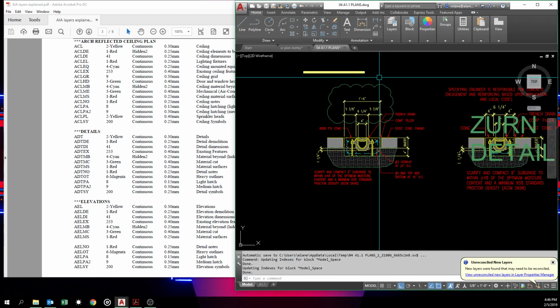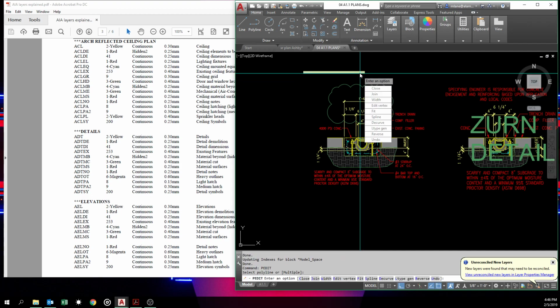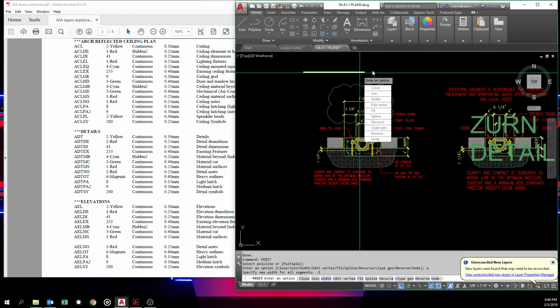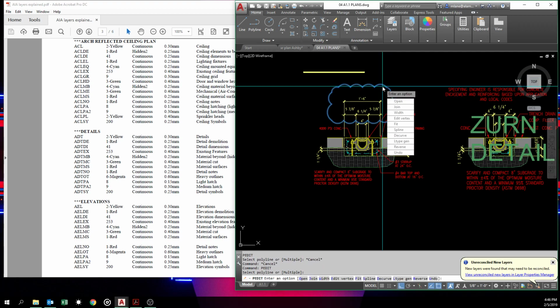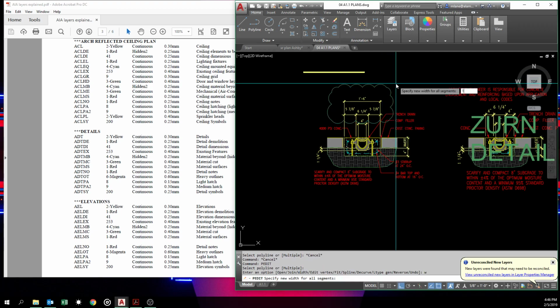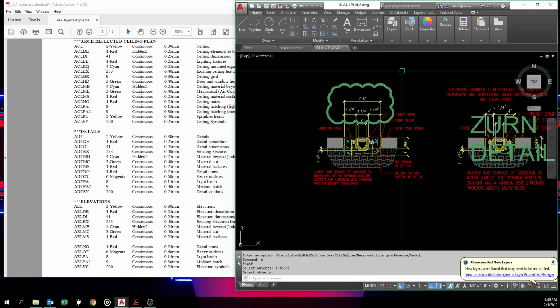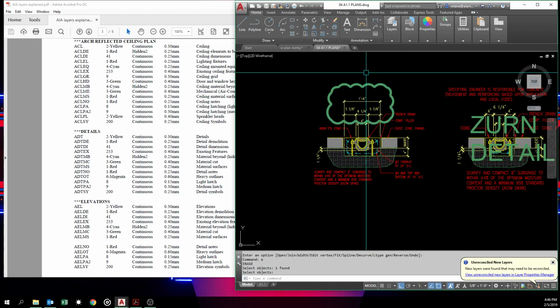I'll talk about this in another lecture, but this is convenient. There's a command called pedit, which is polyline edit. Pick, and we can hit W for width and tell it we want the width to be 0.5, and it makes it smaller. Yay, joys of pedit. And so we'll do these things all the time. This won't print, but it's something that tells the other draft people in the office, this is why we changed this, don't fix it.